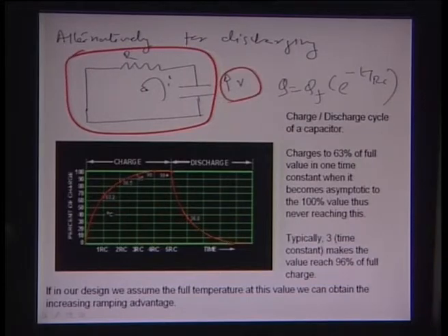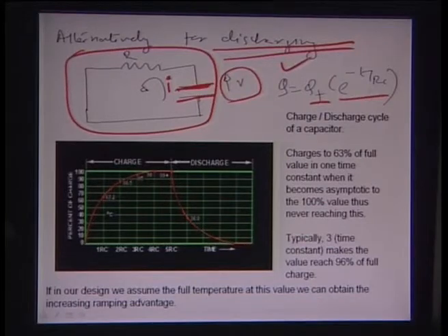the voltage of the capacitor which has been developed over its plates is going to feed the circuit with the current I, and there is a drop across the resistor. So in that case, for the discharging process, Q becomes QF e to the power of minus t by RC. At time t equal to infinity, Q essentially becomes 0, because 1 by e to the power of infinity is nothing but 0. Alternately, at time t equal to 0, Q is actually